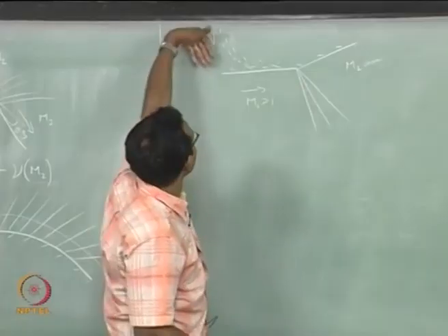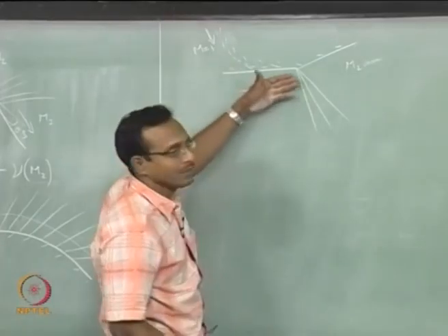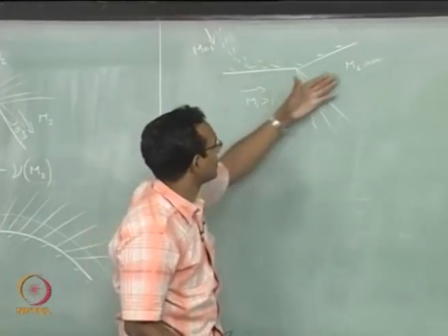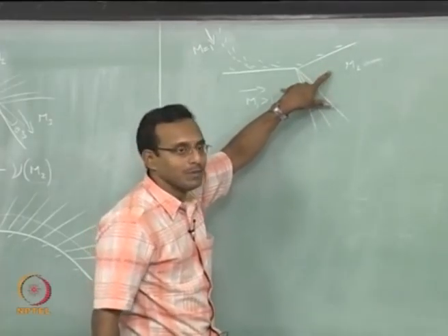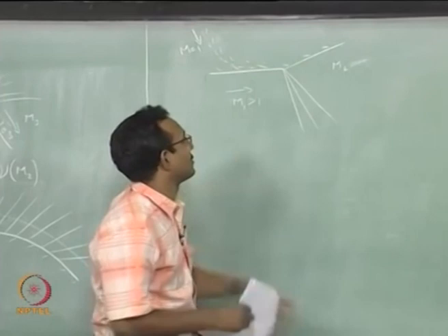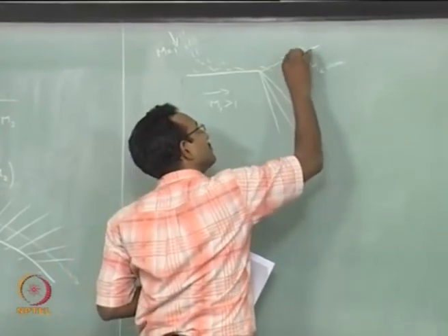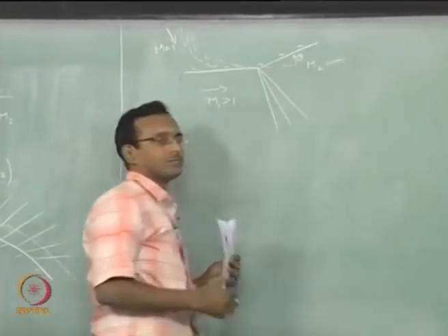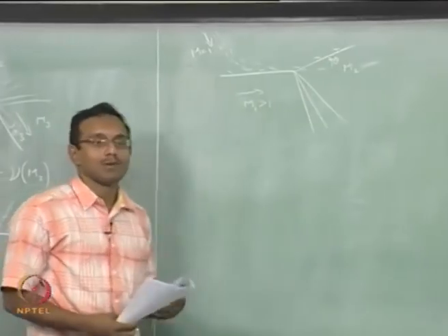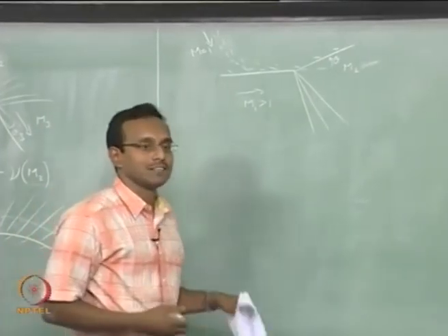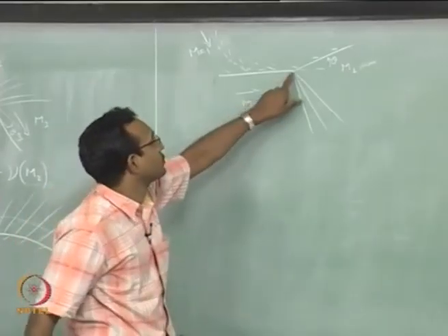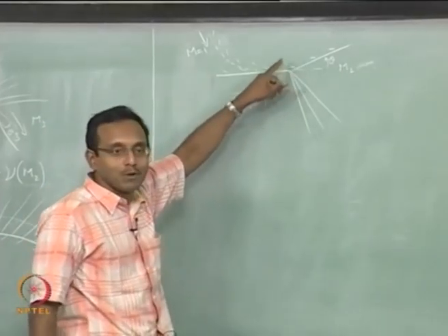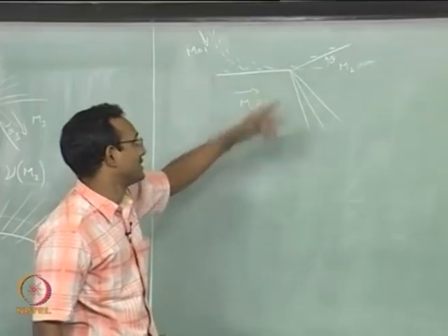The total expansion from the M equal to 1 direction to here will be some value, and then from here it is going to expand more. The difference in nu will be equal to the total deflection here. This will help you understand the problem, so you will never make mistakes in this case. And of course you can always make it a smooth corner or a sharp corner depending on the problem, it should not change anything.